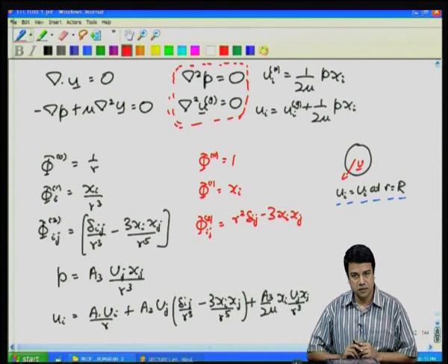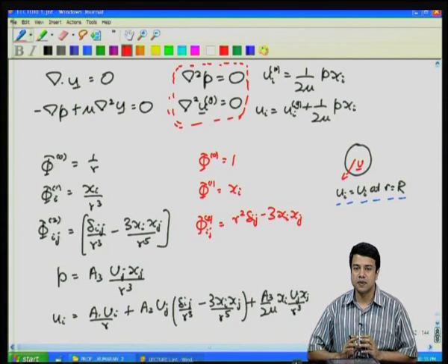We know one solution of this, a scalar solution, that is the solution for a point source, which we had solved in fundamentals of transport processes 1. If we have a point source in an infinite fluid, the system is spherically symmetric, and therefore, the temperature field is only a function of the distance from the point source. We can of course place the origin of the coordinate system at the point source without loss of generality.